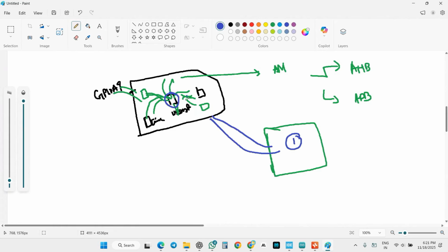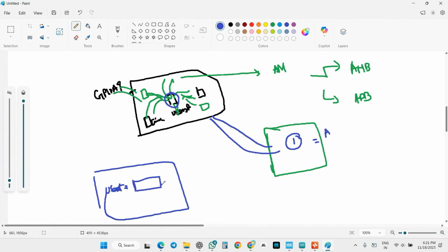While it is dumped into the chip, you specifically write the register name. This is the register I'm going to use, because everything has an address. UART has some specific address. If you enable that address, in that specific address, whichever bit you toggle to one, that bit is going to be toggled, so your UART has been on. If you just toggle the GPIO A through that bus, it gives one clock pulse and it is going to be on. When it is on, your microcontroller is now ready to do some function. So this is how it actually happens.